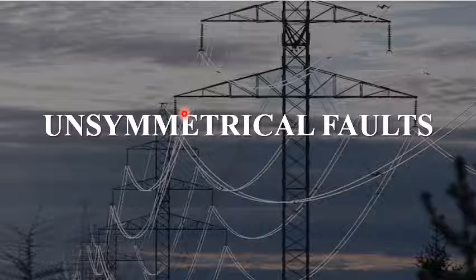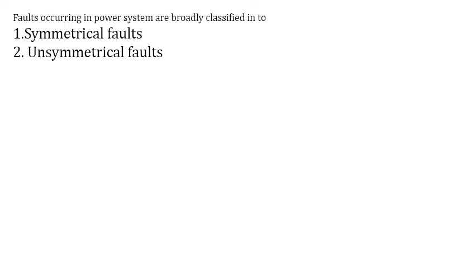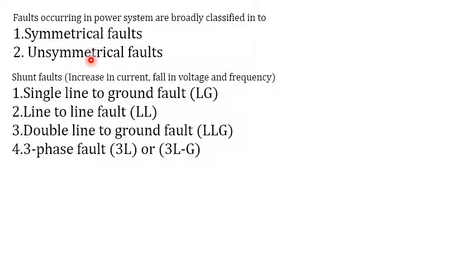Next we are going to discuss the concept of symmetrical fault. There are different types of fault occurring in a system, broadly classified into two types: symmetrical fault and unsymmetrical fault. Other than this, we have shunt faults and series faults. The shunt type fault involves a short circuit between the conductors or between the conductor and the ground.